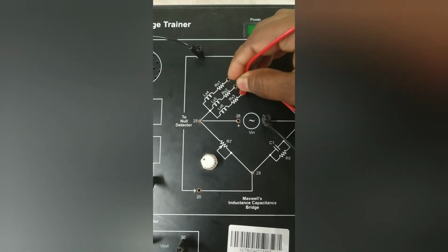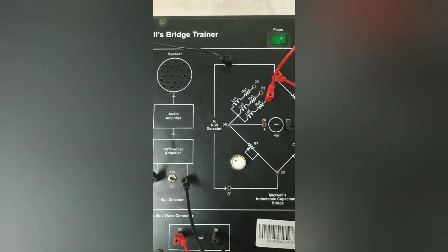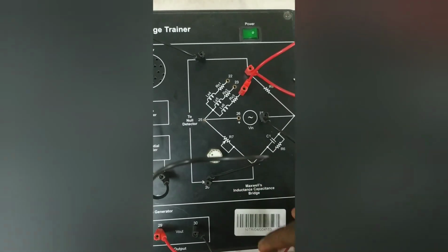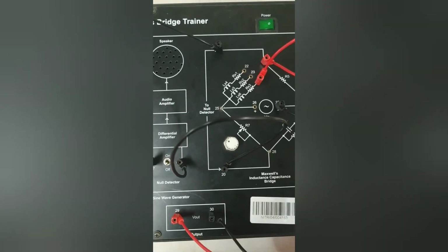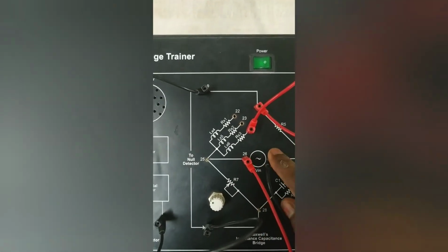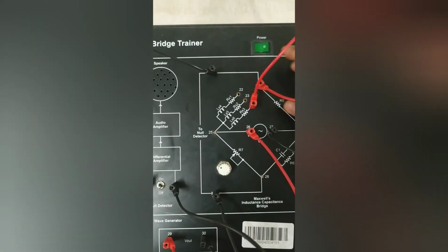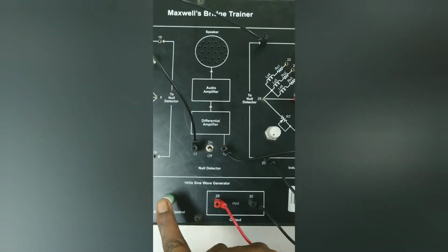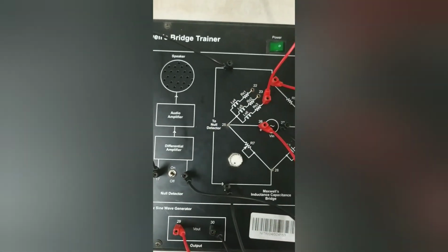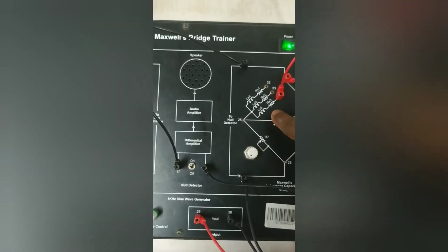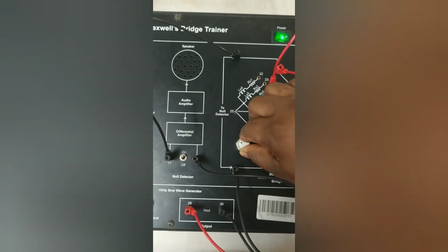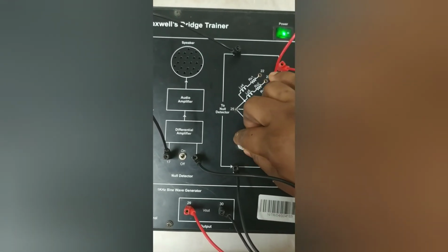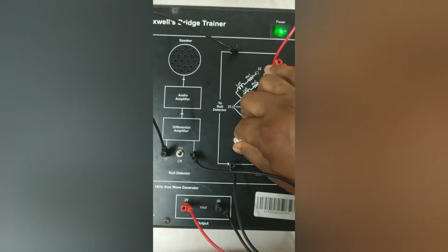So 21 24, next 17 to 19, 18 to 20, and the same sine wave generator connect to 26 29 and this one 27 to 30, and next this potentiometer must be in minimum position, amplitude control in maximum position, then switch on the power supply and switch on the null detector and rotate the potentiometer very precisely where the noise is minimum. That was the balance condition of this bridge.